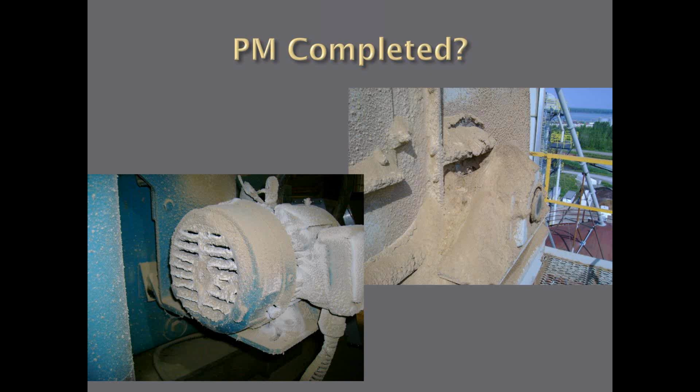Well, the wind was blowing real hard that day and the bucket elevator was shaking around. I didn't want to go up there. Well, that's okay. Good excuse. But don't check the PM off that it was done. Because if I'd have known that, I'd have carried the grease gun up there Saturday morning and greased the bearing.